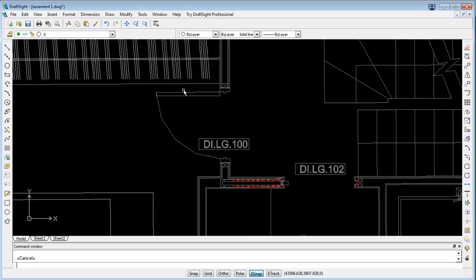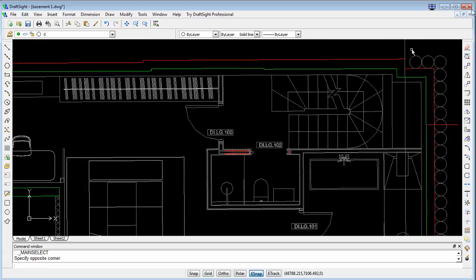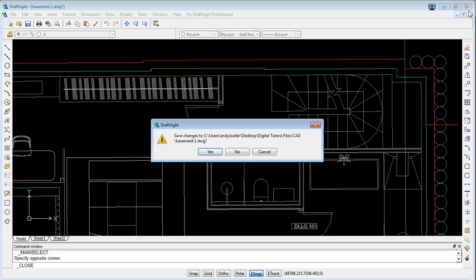So I just type in DIST, hit enter, and click, and that will give me the distance between the 2 points that I clicked, and that distance is 900. So that would be 900 millimeters, which is a large door, but it's a door nonetheless. So we know that our CAD scene is in millimeters.